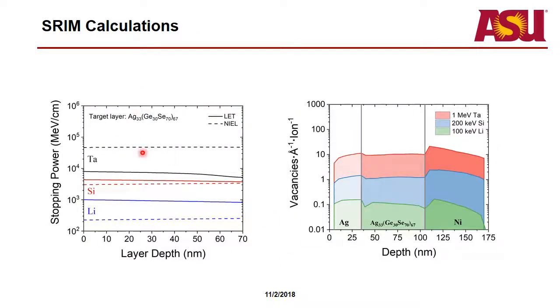So here, this is the split of the different energies. Like I said, this is a combined environment. You have an LET, which is more of an electrical interaction. And then you also have a non-ionizing energy loss, which is going to be the more kinetic interaction. So you'll have energy loss that doesn't necessarily result in ionizations. It's more that you're punting atoms elsewhere in the material.